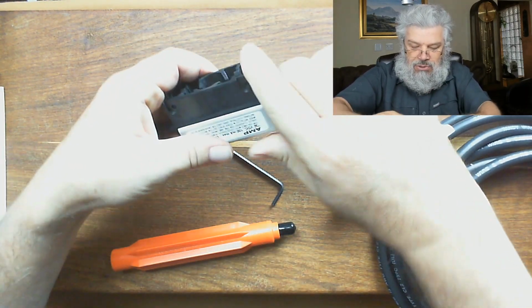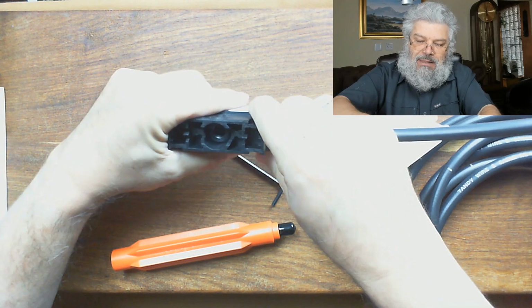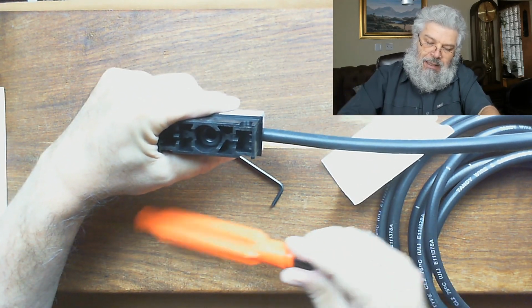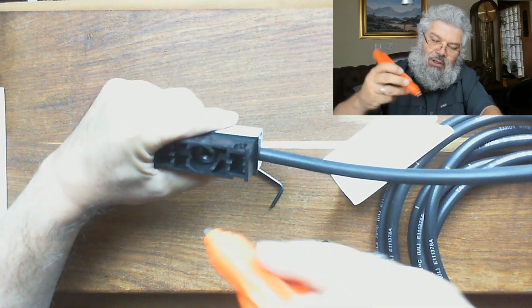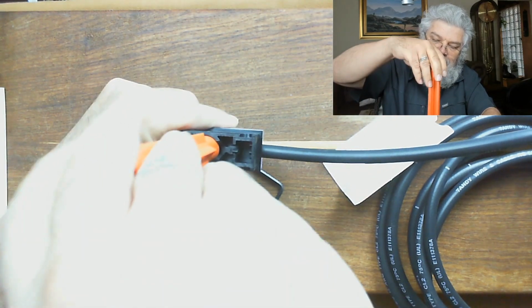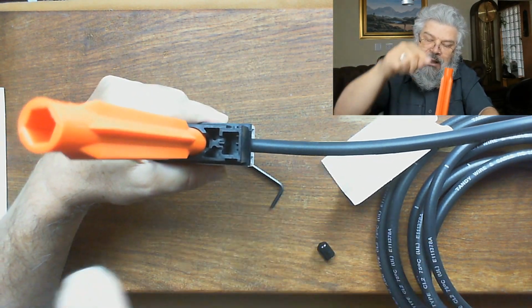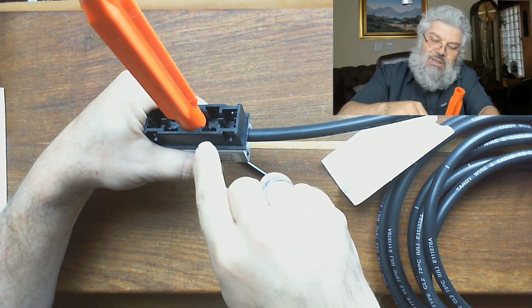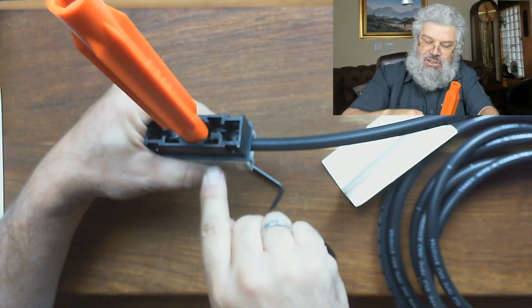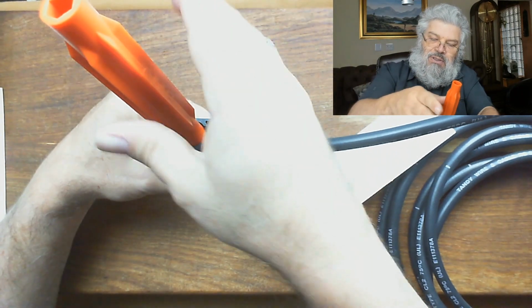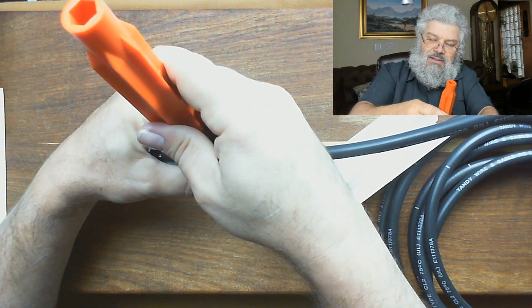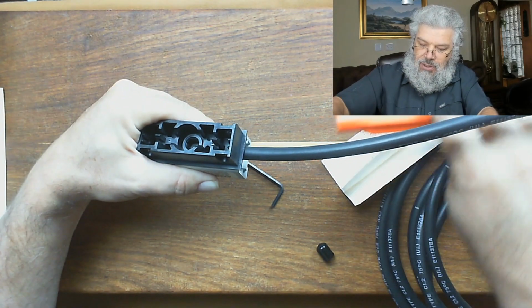Now we need to get the long tooth in. And for that, I will use my drill, and I'm going to put it into this plastic part, and I am going to drill a hole. So this goes through this plastic outer coating. It goes through the braiding, and it's just nice, long enough so that it touches the copper core. So nicely guided here. There's very little that can go wrong.